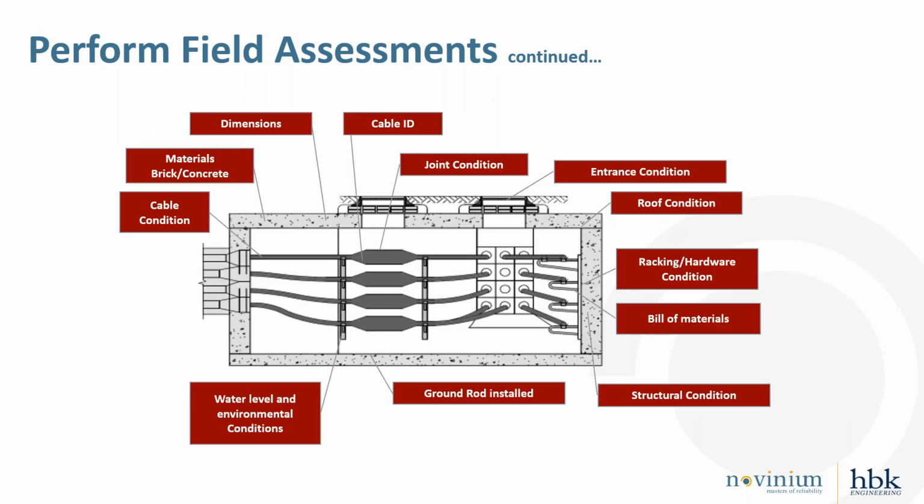To get into some detail about the elements that we do capture during an assessment, we're trying to be as comprehensive as we possibly can with all elements. In the ComEd program, our assessments capture data pertaining to the electrical, mechanical, structural, and environmental aspects of each manhole. Each cable in the manhole was evaluated for a number of conditions: its jacket condition, its racking, joint conditions, leaks, exposed conductor. The grounding system was evaluated.